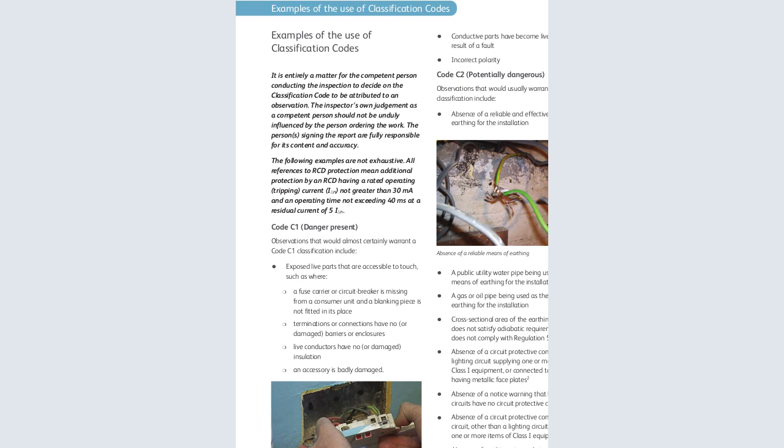Yes, proceed. Then we've said when giving the final condition, you either say it is satisfactory or unsatisfactory. You avoid saying what? Poor. We avoid saying poor or rewire, because when you say poor or rewire, it's like you are looking for some job for yourself and it's not professional. Okay, now let's proceed.